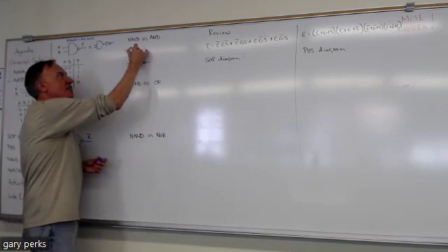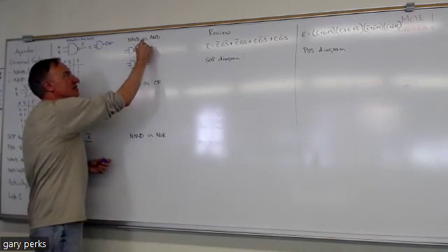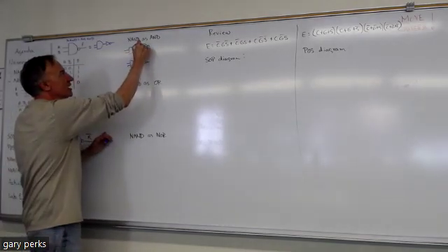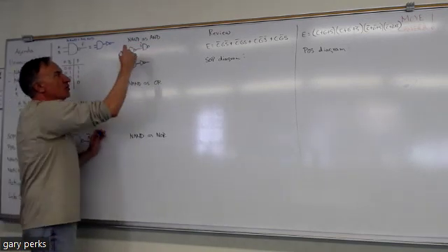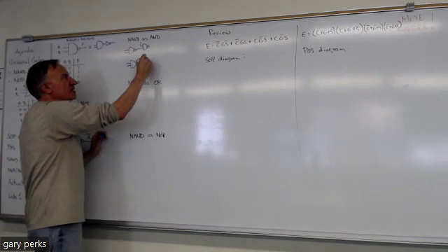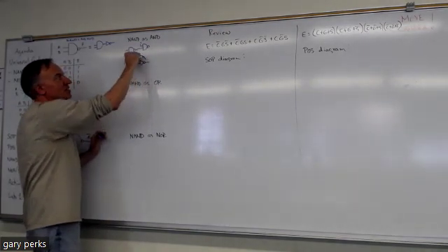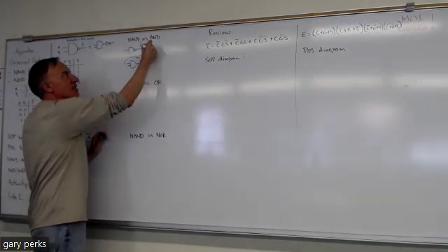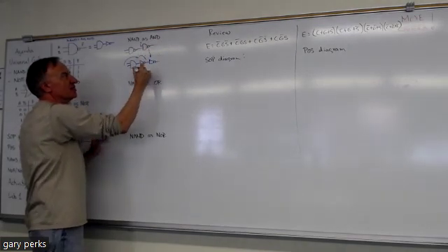Now, if I put a NAND gate that's connected as an inverter, so say I use the one where I connect one input to a one, like that. Well, this AND with the inverter on the output is equivalent to this NAND. And now if I put an inverter here, this NAND is an inverter.